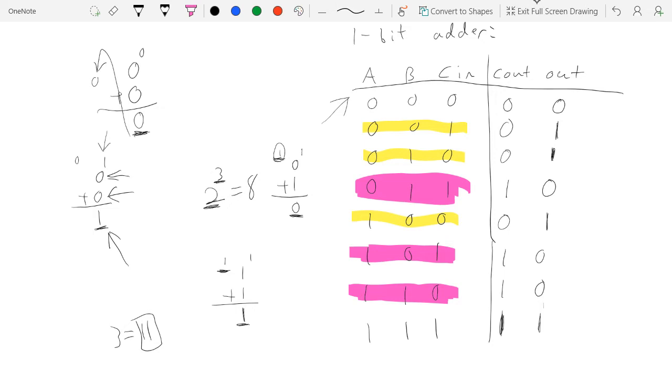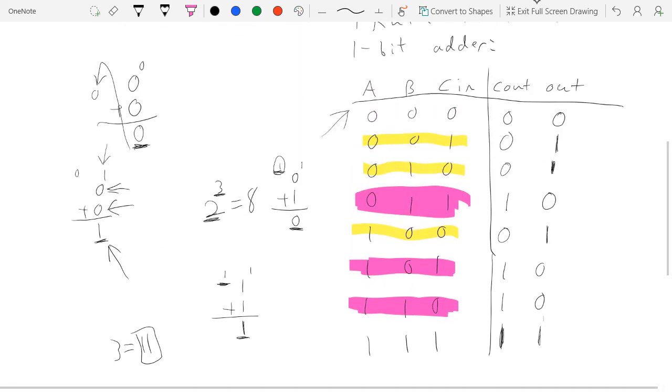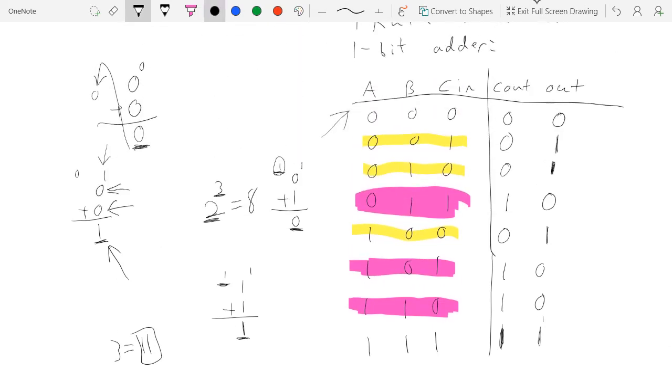We've got our truth table now, and now we want to make a 1-bit adder circuit from this. And so we're going to make a sum of products expression here. Specifically, we're going to make the canonical form of our sum of products expression, and remember that that just means that it's as hairy as that expression will ever get. We can't make it any messier. So we can actually use Boolean algebra if we wanted to simplify that canonical form expression a bit. But we're not going to do that. We're just going to provide the original canonical form, and we're going to build the circuit strictly based off of that.